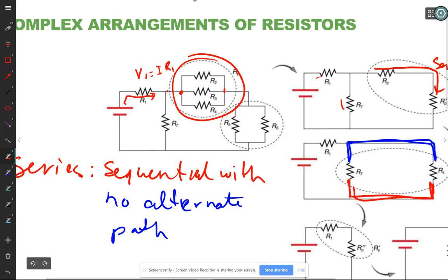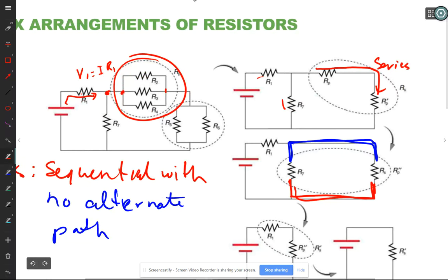And so that means I can calculate the voltage here by taking the voltage from the battery minus that voltage drop. And then I can determine how much current goes here by taking that voltage difference in this resistance. And if I come to here, I can actually take the difference and calculate the current, but then I have to come to here to calculate the voltage drop across there. And so I can go backward through my circuit and calculate what the voltage drop across each element is, what the current through each element is.